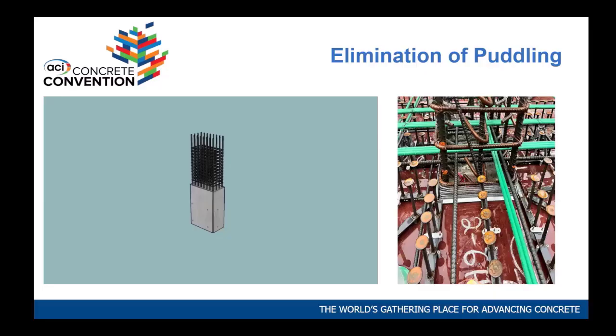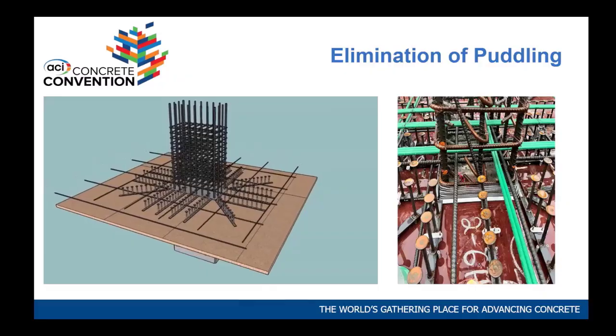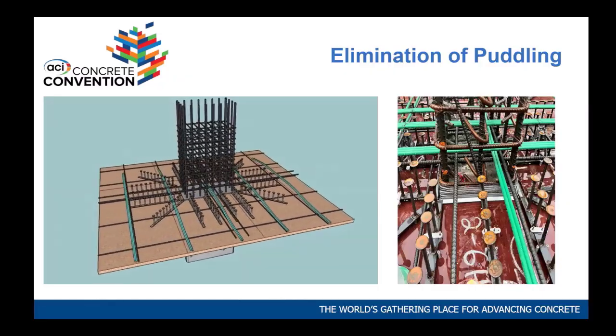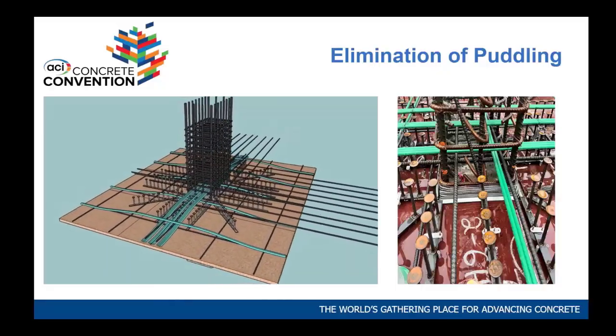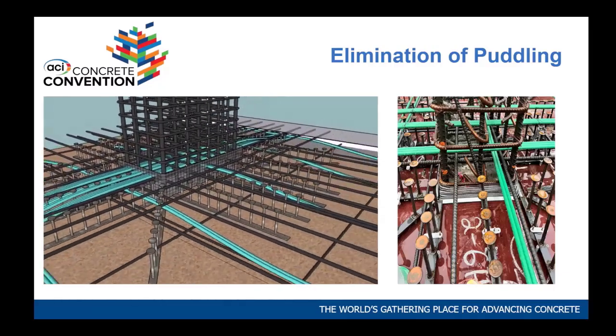I'm going to click to see if that video will work. Oh, yeah, it does. So these are the stud rails. This is rebar, and these are the shear bars that we put into this. The green is the PT cables. You can see them here too. And then this is the top reinforcement. And then you put in this stay form.